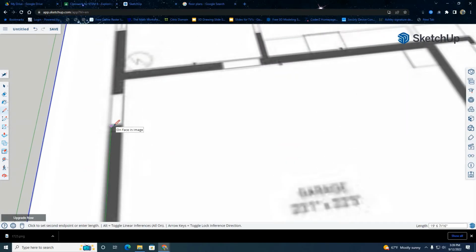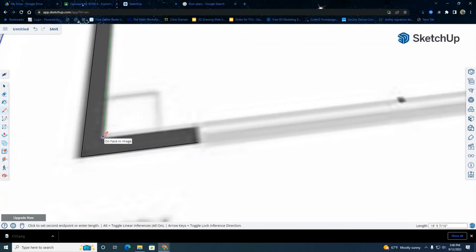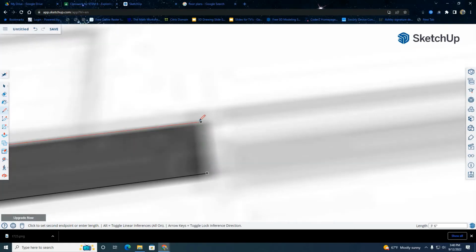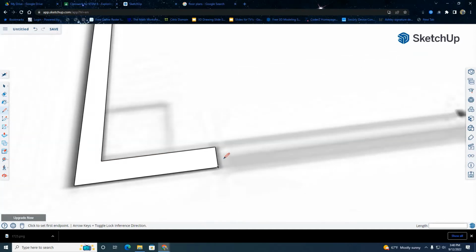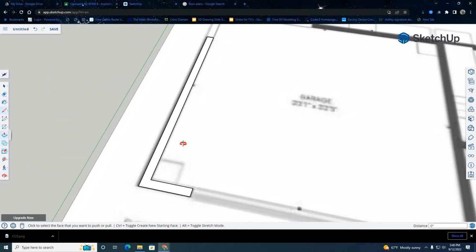So I'm gonna go up to my next door. This is my side garage door. I'm gonna just keep clicking on the wall. So this is a point where I stop. I start turning around. Now, as you can see here, I have it auto connecting, so I know that I don't have to guesstimate. It stops right here. I just click once and I'll just carry that through. Now you notice that that wall just filled in and it's time to raise it up.